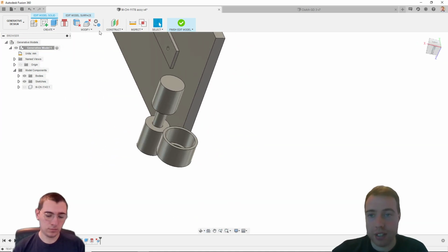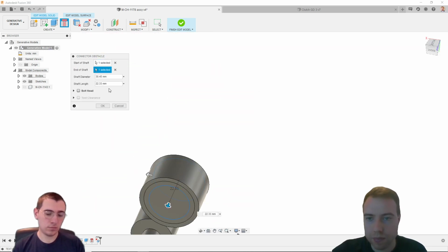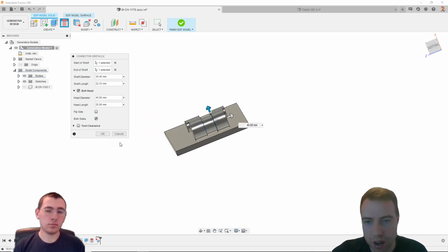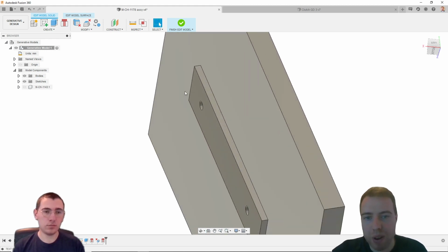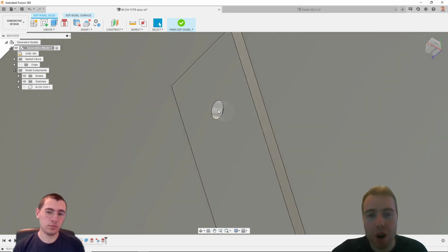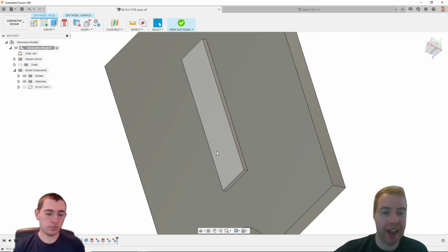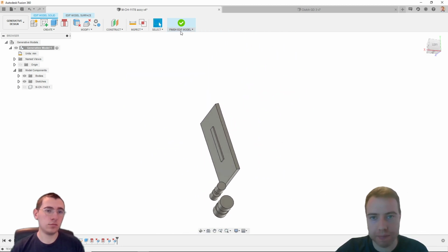And then I'm going to create a connector obstacle. Again, we want to leave space either side. Yes. And then we've also got some holes here. What I'm actually going to do in this case is get rid of those in our generative design study, and then add those in at the end once I've created my geometry and got my outcome from generative design.